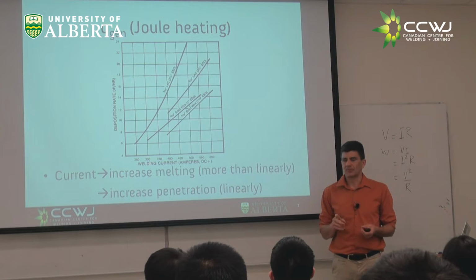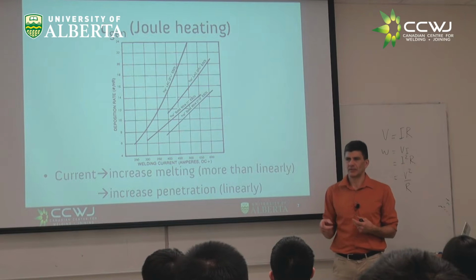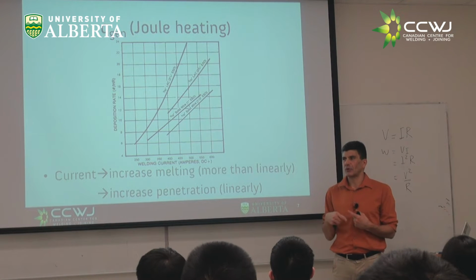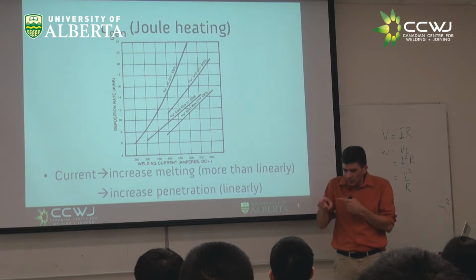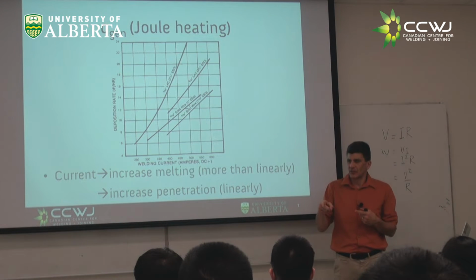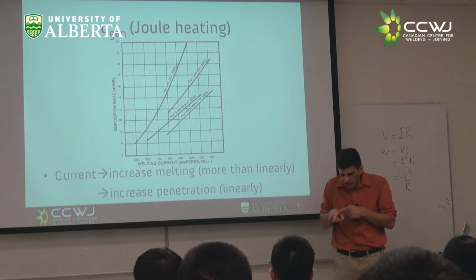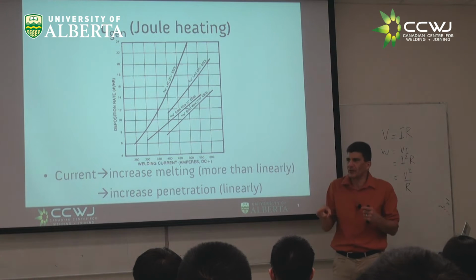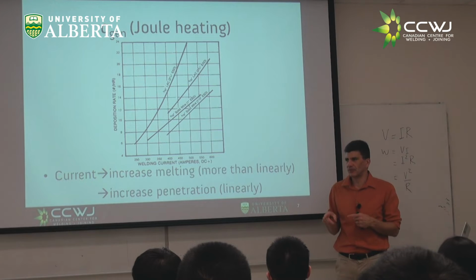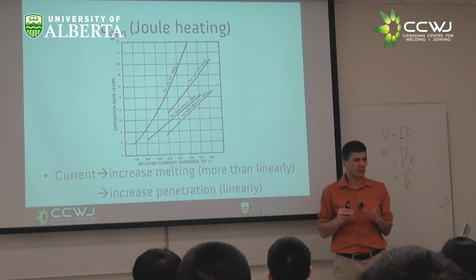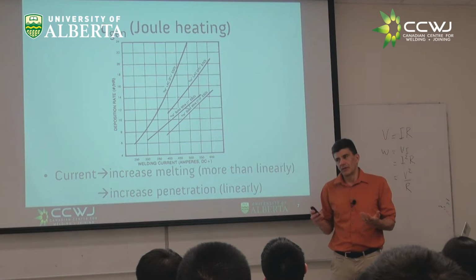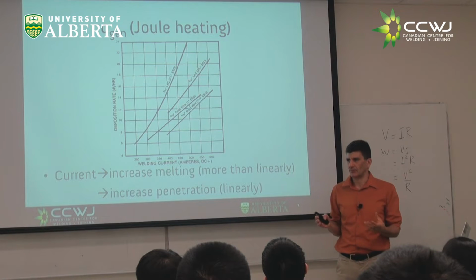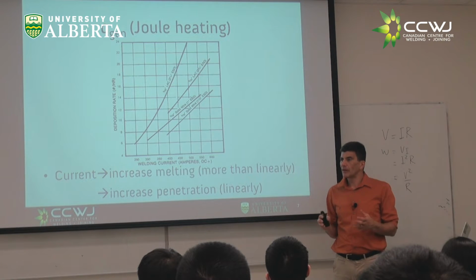The other problem is, remember when we talked about cast and helix of the wire? The wire is rolled. So if you have too long of a stick out, the wire comes a little bit bent. So as the welder is welding, it's going to see that the wire is wandering all around. And if it is an automated process, that's a big problem, right? So people don't have very long stick outs for that reason, the cast of the wire. Now, there are ways of solving this.